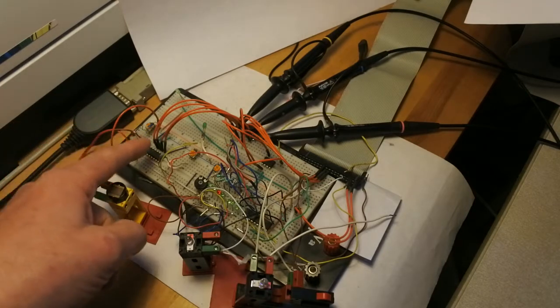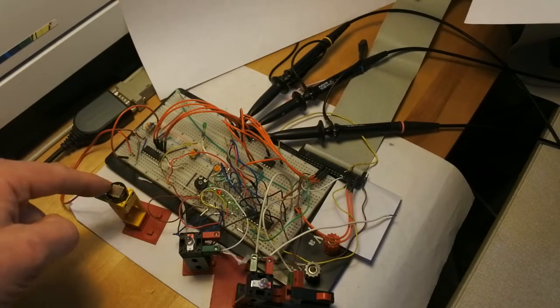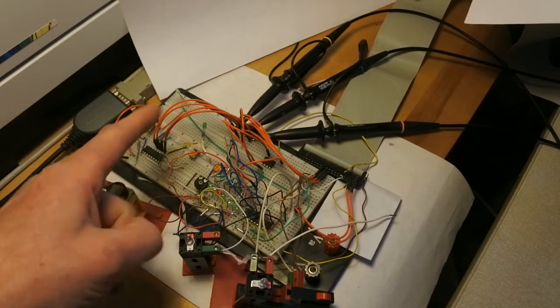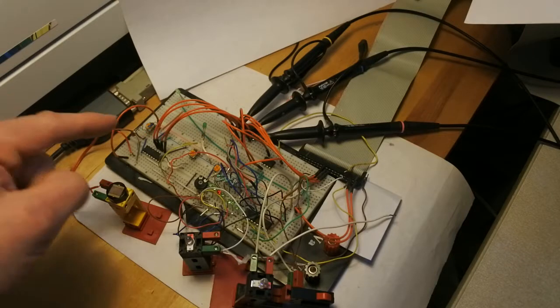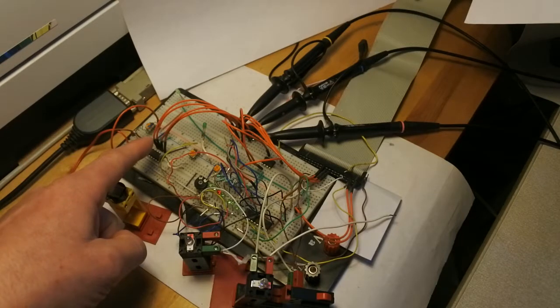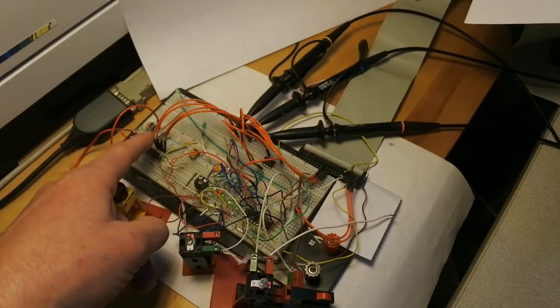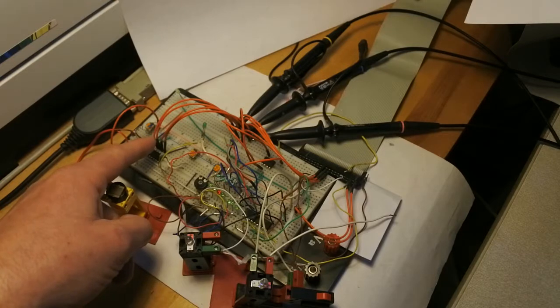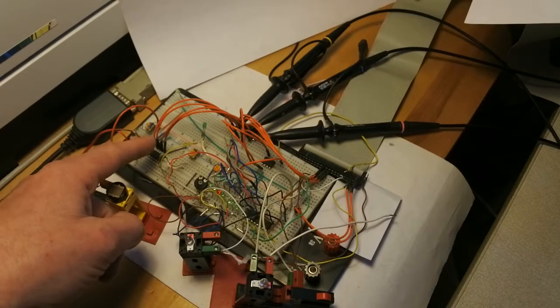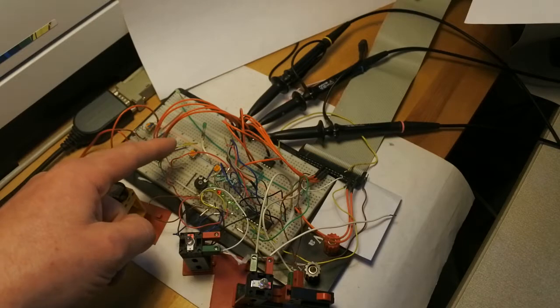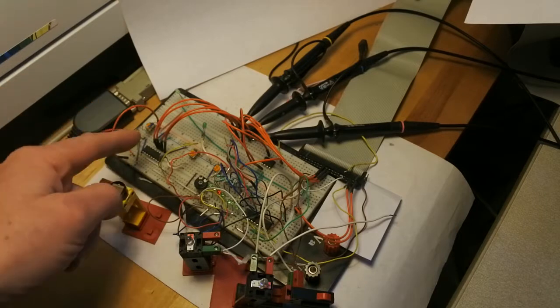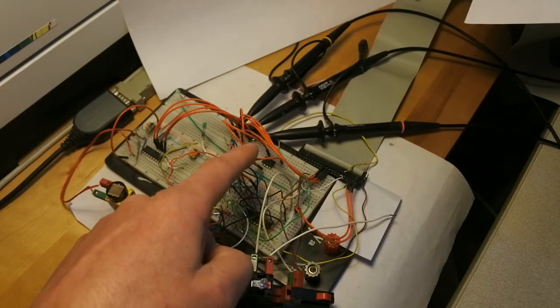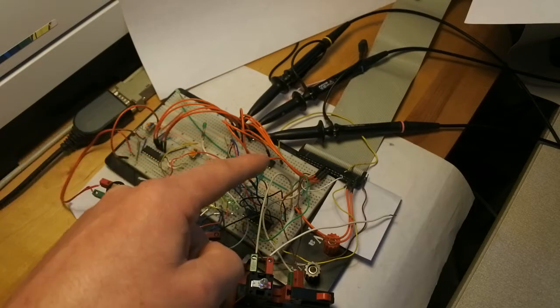Also connected to SPI is this analog to digital converter, which goes that way, and this is SPI full protocol. Full protocol has 2 wires, one master input slave output, and one master output slave input. This means in technical terms full duplex. This one, because of 3-wire, is half duplex.